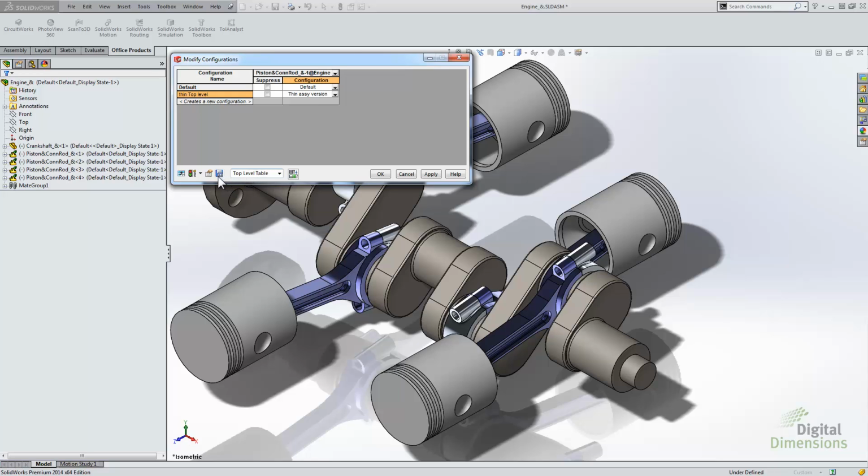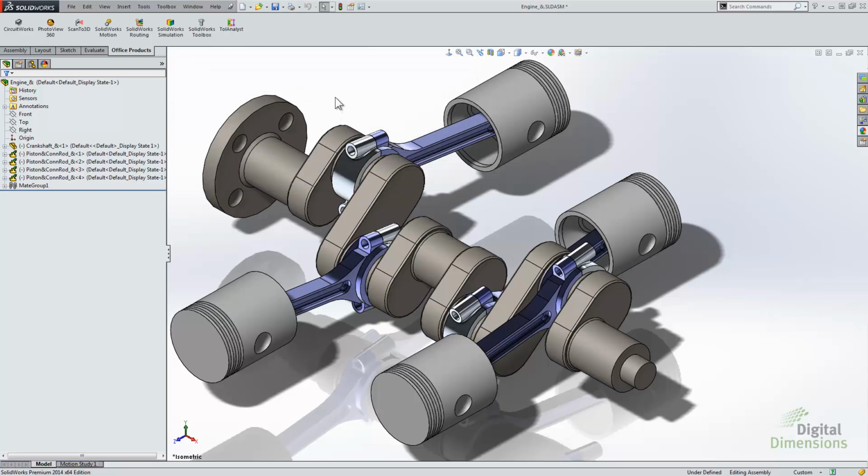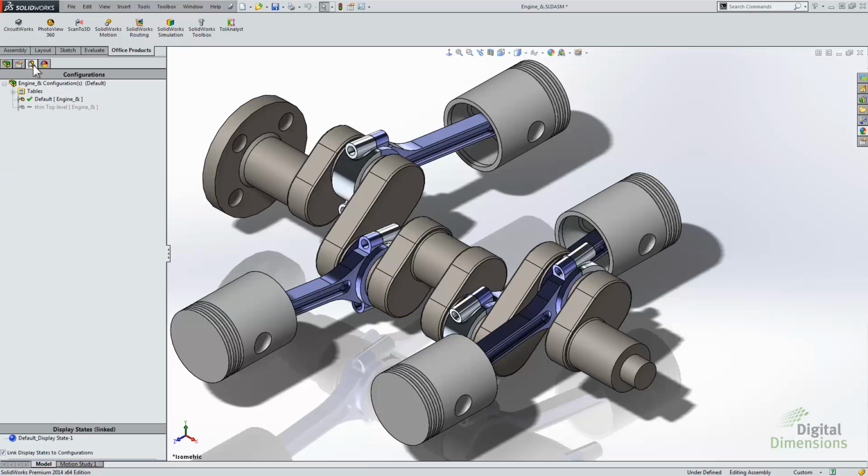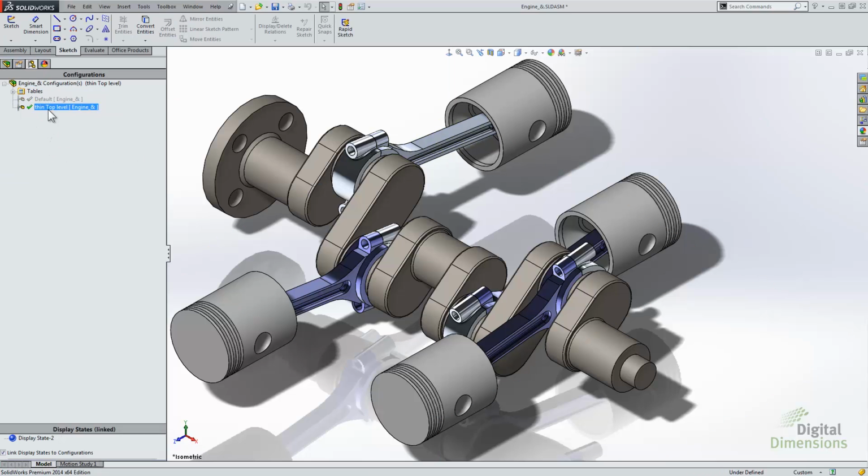But yeah, getting back to the mate method, you can actually do a distance mate, and you can configure the dimension of the distance mate. And again, easy enough. You see here that we've got the different configuration. And again, it's only changing that one instance that I right-clicked over. I still have my tables folder, so you'll see the table that I created here.